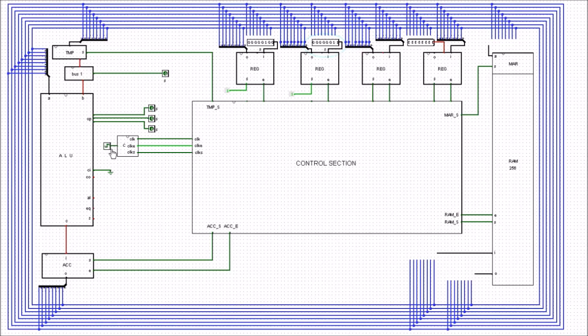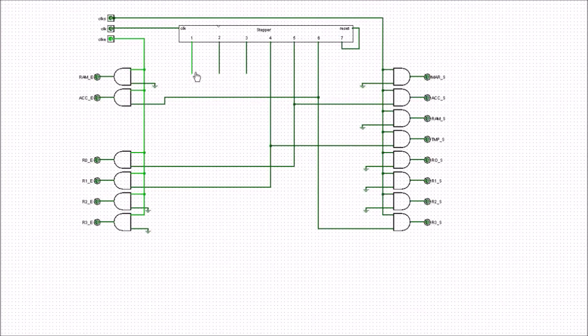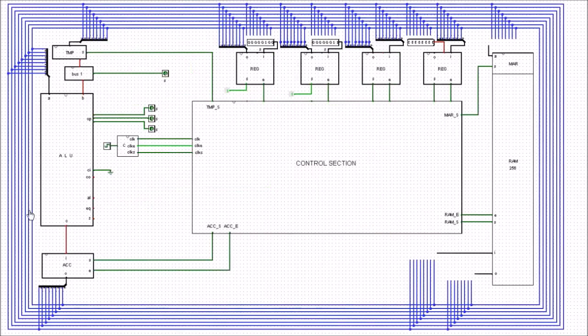Now it takes 4 of these clock pulses here, which is the master clock, in order to work through the enable set process. So there's nothing going to happen for the first 12 clock pulses because we come down in here, these aren't connected, these 3 here, so it takes 4 clock pulses to go through this one to that one to that one. So nothing happens until the 12th clock pulse. So let's go back up to the top and we'll have a look at that. So if I pulse this 12 times, 1, 2,